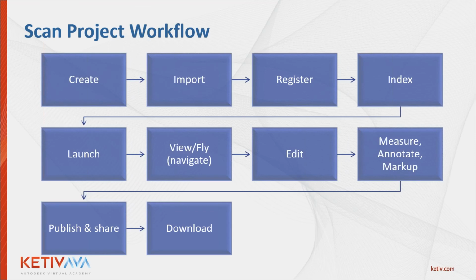And when you're doing laser scanning, there's a specific workflow that goes with it too, by the way. This information is available through Autodesk as well. I thought I'd put it here together for us as a summary. Basically, you have to create a project, and then you import the scan. When you import the scan, it goes and registers it, which really means that it's going up to the cloud and stitching it all together. From that point, you index it and bring it into the ReCap software to be able to navigate it, fly through it, and figure out what parts of it you actually need so you can edit it. Therefore, you can then start to measure, mark up, annotate, and share it with others or download it for yourself to be able to reuse.